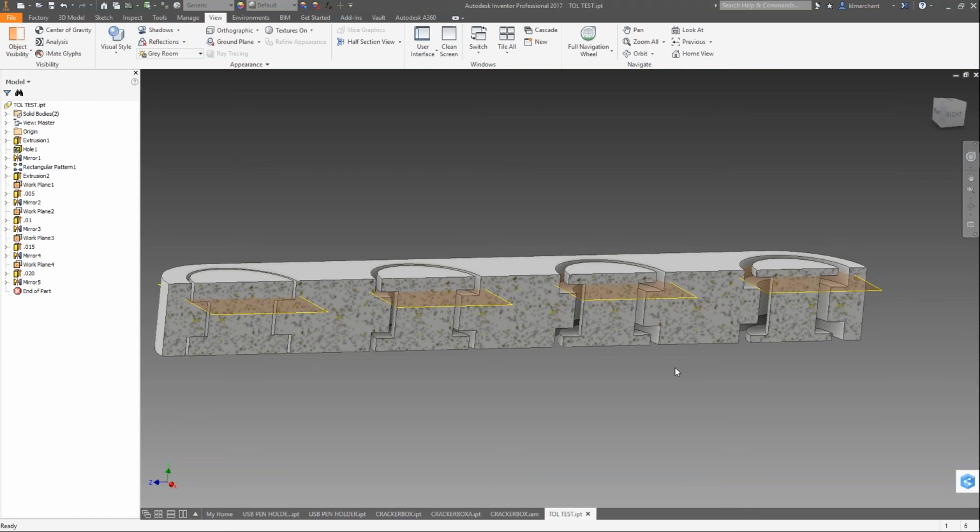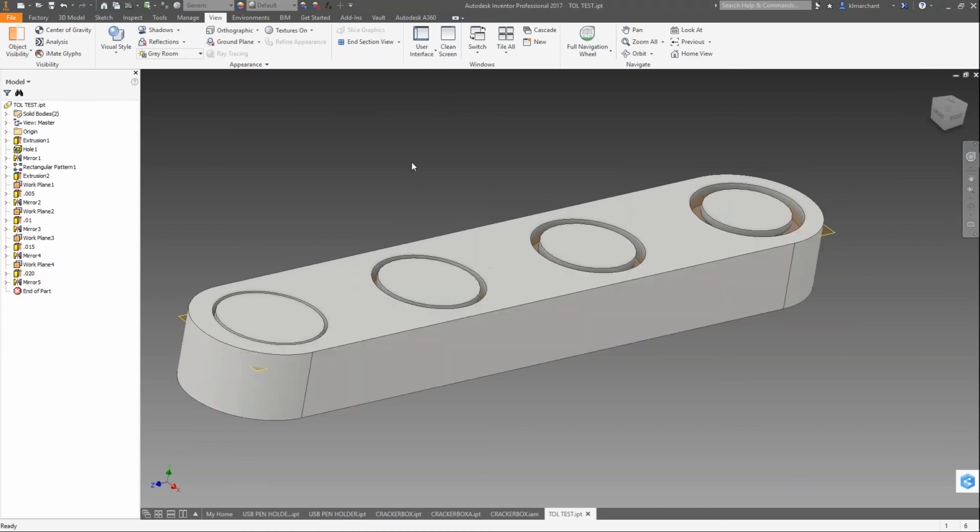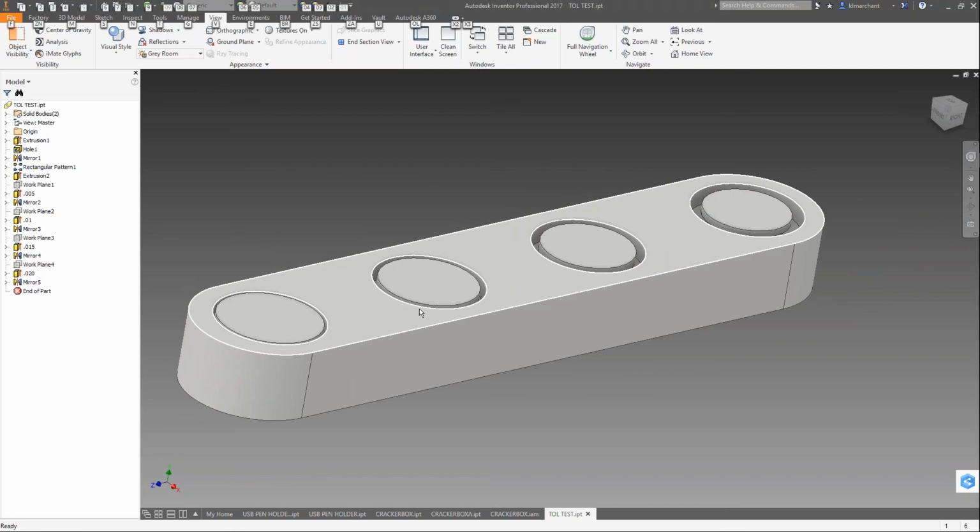CJP, again, we have the wax, or sorry, CJP uses a powder in there, as Barb alluded to. And so that gypsum-like powder, when it is unbound by the binding liquid, becomes a support material. And so we take that part out and basically give it the equivalent of a little shake. We can use vacuums and a little bit of air pressure to blow that powder out of those joints, and then move them. And so we can see what kind of clearance we can get out of those parts.